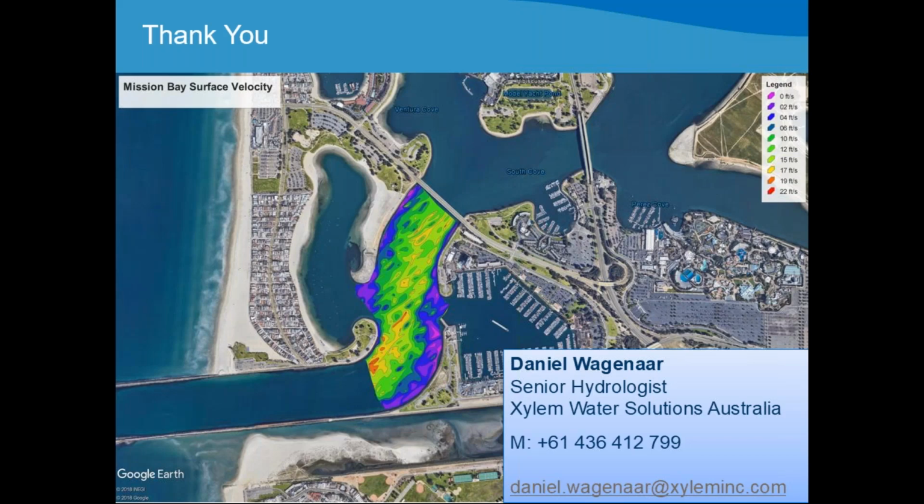So one way of finding this out, and we haven't discussed it in this webinar, is to look at your SNR profiles, signal-to-noise ratio, that's displayed in real time. And if you see one or two of the beams, or even more, separating from each other. So normally the SNR profiles should be closely matched. They're not going to be exactly the same. And depending on the profiling technique, if it's pulse coherent or incoherent, pulse coherent is a bit more noisy because it's smaller cell sizes. Incoherent is a bit more faulted because it's larger cell sizes.